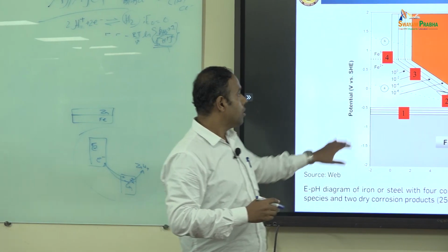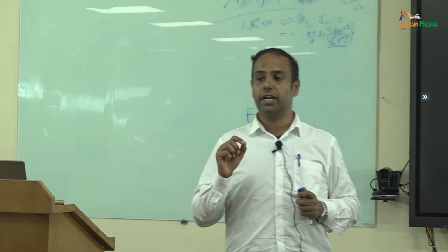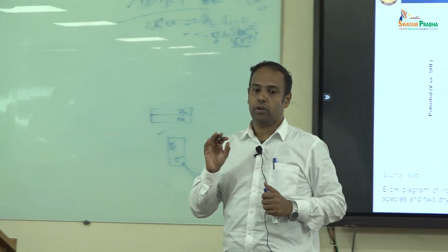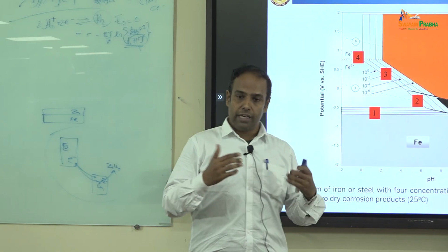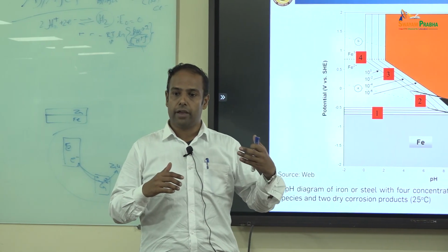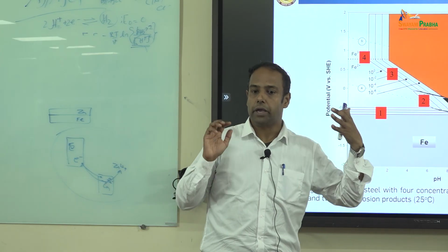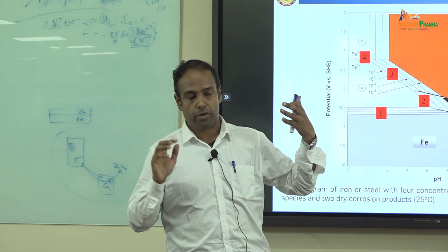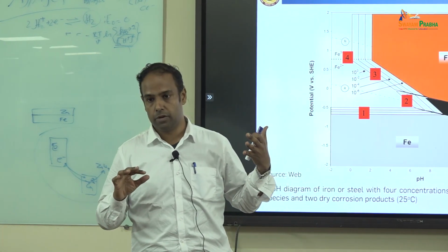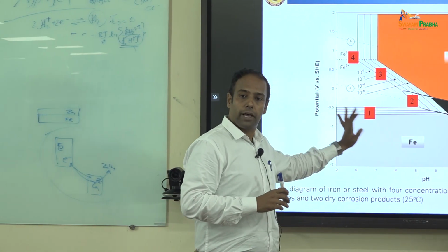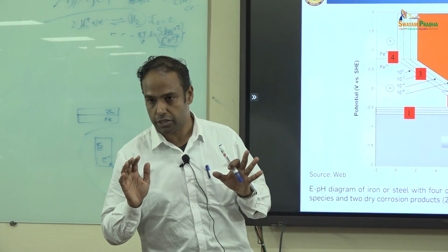So this is how you interpret a Pourbaix diagram for identifying the corrosion behavior of a metal. If you are starting with a new metal system, you can easily look into a Pourbaix diagram and identify what environment keeps it as a passive system, or as an immune system. So the Pourbaix diagram gives us much more from the simple concept of thermodynamics, right.